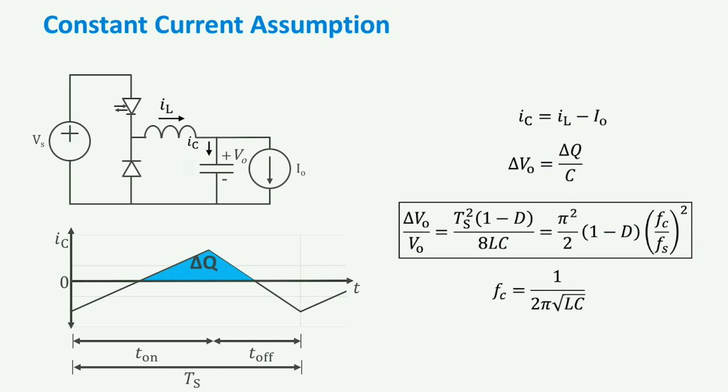Do observe that the voltage ripple becomes small when we reduce the duration of the switching period, implying a high switching frequency. The ripple also becomes smaller if the inductance and/or the capacitance is increased.